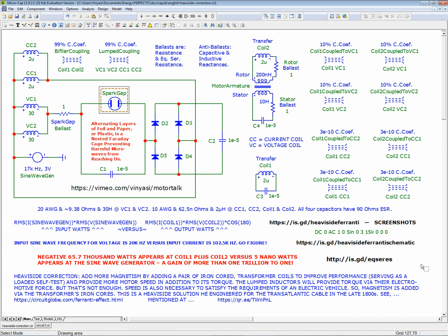So what I read recently is that equivalent series resistance overheats a capacitor. It eats up the dielectric material, literally like paper aging in a book, which turns yellow and brittle and gets holes in it. Well, a lot of the dielectric material of capacitors is paper alternating with layers of foil. And I guess that's one way to do it. The paper weathers and ages just like the pages in a book. And when you get holes in it, then you've got yourself a short. It slowly degrades, and before you know it, the capacitor isn't good for anything because it's been stressed.